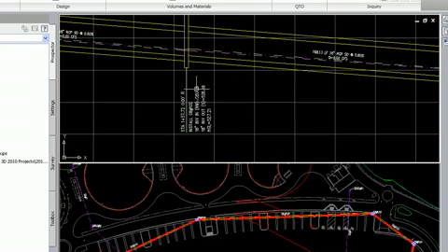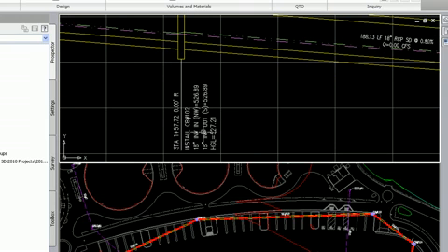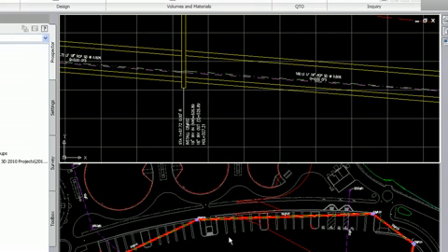And further, we can label that hydraulic grade line. We can make the elevation of the hydraulic grade line show in a label for the drainage manhole. So really good stuff there, the integration with the storm sewers extension.